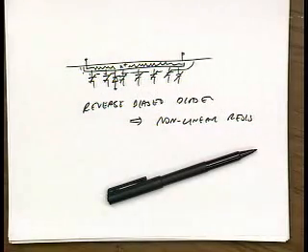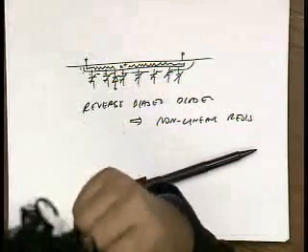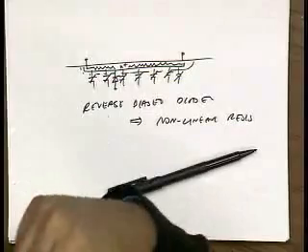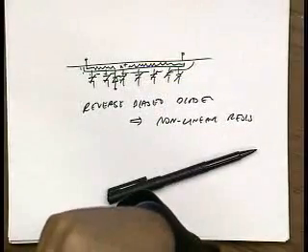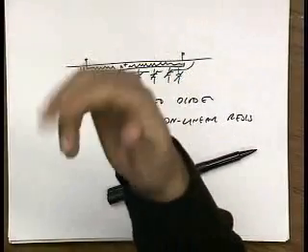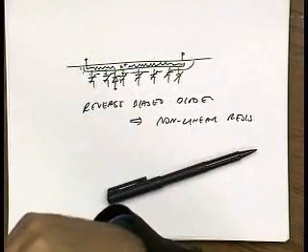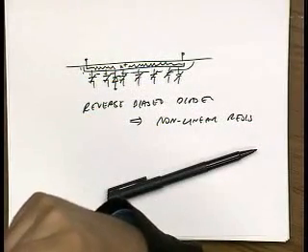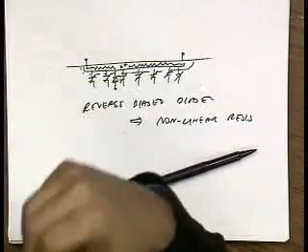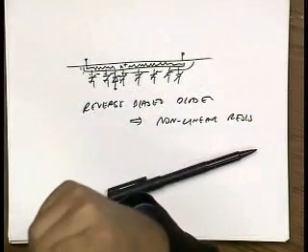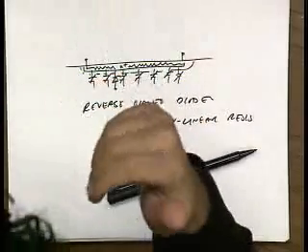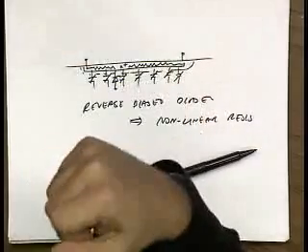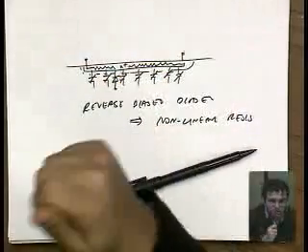Okay? But you're also right. There's temperature variation. There's also, more importantly, process variation. The resistivity will vary quite a bit for a diffusion resistor because it's not necessarily a very well-controlled parameter. As a process engineer, you just want to get the resistance low enough in the diffusion regions. You don't necessarily want to target a certain value.